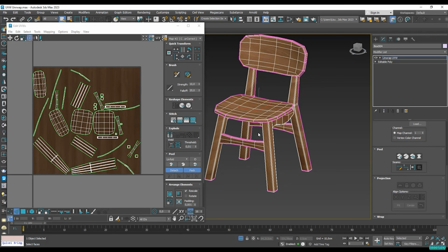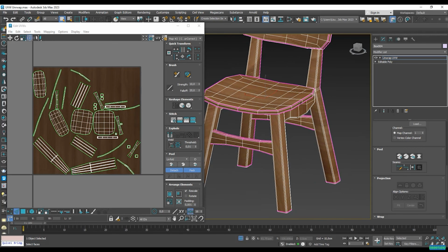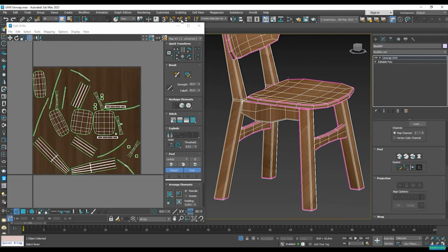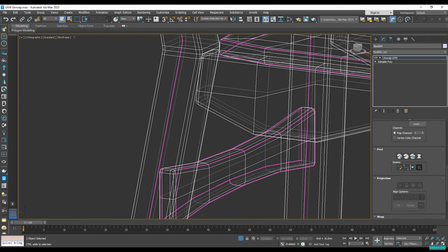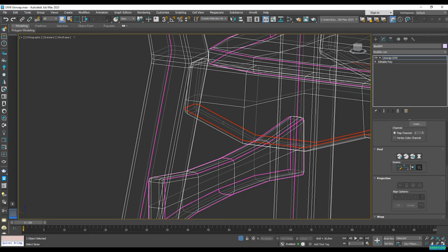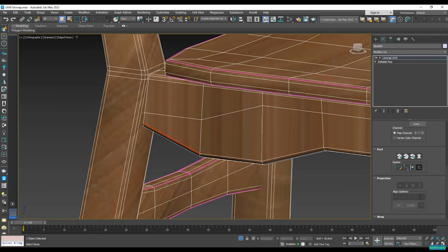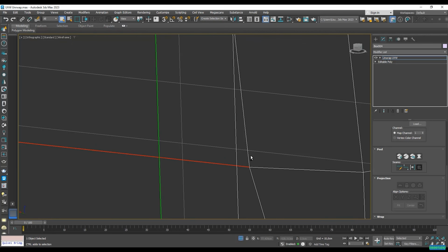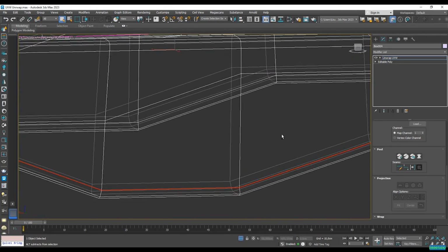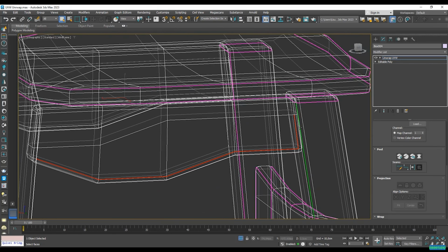Okay, so we're almost done here. We only need to work on these two railings at our lateral sides. Okay, let's close this, and these ones are not going to be that tricky. So let's separate the face again. Make sure not to be selecting any of the back edges there.